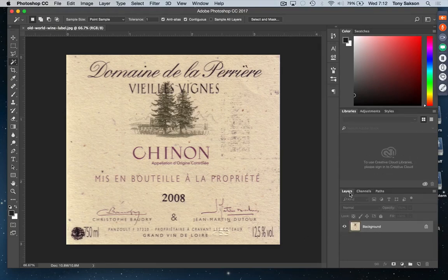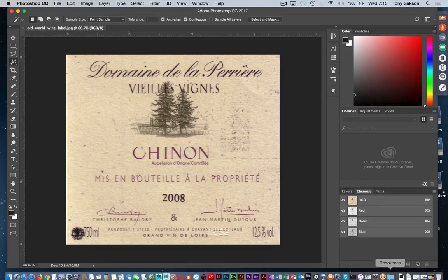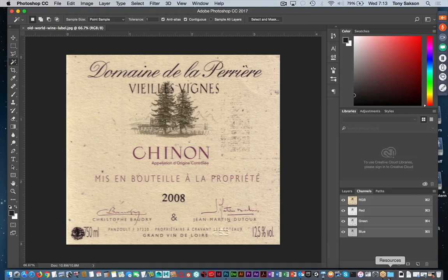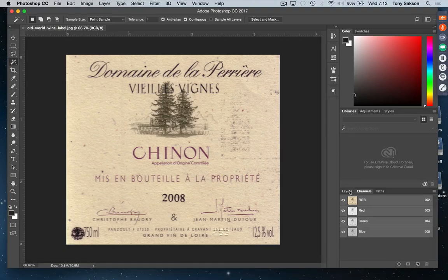All right, so normally everything in Photoshop will usually bring up your image in channels. If I take a look at it in layers, you'll see it is RGB, but there is no alpha channel. And the alpha channel is what we use to plug into the presence channel of the Pixar surface. All right, so like I said, in order to create an alpha channel, I need some kind of border around the image. Right now, there's nothing there.